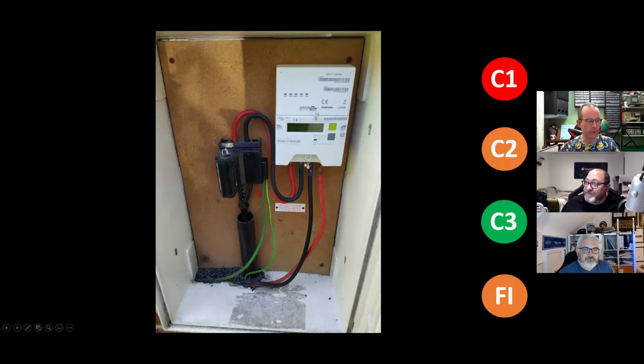Exactly. Okie dokie. As everyone said, C2, C3. I'm C3, by the way. I'm going to argue with John and say it just requires improvement. I would carefully observe the utilization. John said that there's no electric heating. It's not a large house. I should imagine subsequently till the next periodic inspection and testing, there's probably little to no cause for concern. So I might be okay with the C3.